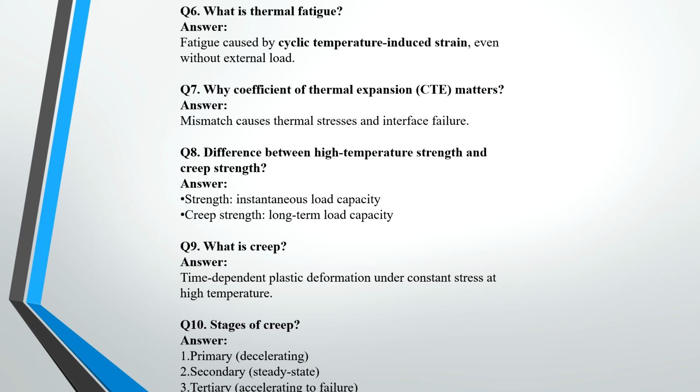So what is thermal fatigue? Thermal fatigue is caused by cyclic temperature and the induced stress, even without external loads. So this thermal fatigue is due to the cyclic temperature. Why does the coefficient of thermal expansion (CTE) matter? Because a mismatch causes thermal stresses and interface failure.